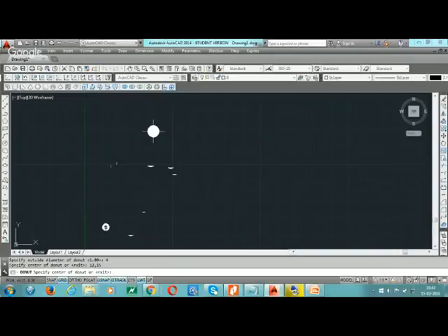And again we can make it, the command is not yet over. You have to press enter, or if you want to repeat a donut, then you can pick up the next points. Now let us give these points in relative mode. All right. So from this point, we want to draw a donut which is at a distance of, again, let us say 12.